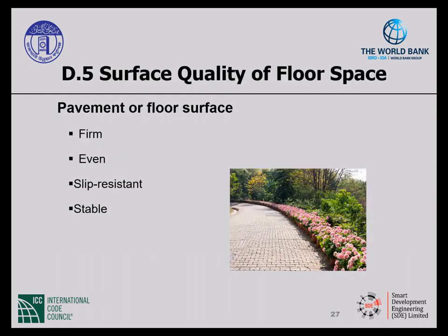Surface quality of floor space for pavement and interior floor surface. All pavement or floor surfaces required to be accessible shall be firm, even, slip resistant, and stable. Notice I didn't say smooth. This isn't required. As you can see on the slide on the right, this is a pavement out of brick pavers, and as long as the gap between the pavers is not more than 12 millimeters, this is completely compliant.